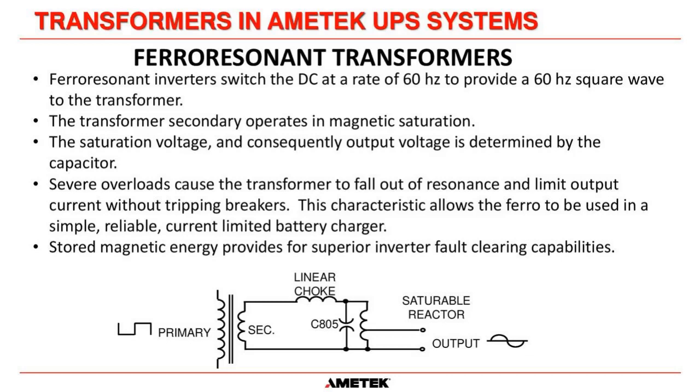Another advantage of the ferro is stored magnetic energy provides for superior fault clearing. Ferros will clear faults in a distribution system. If we have a proper distribution panel, preferably with high-speed fuses and switches, ferros will do a great job of clearing faults out there.